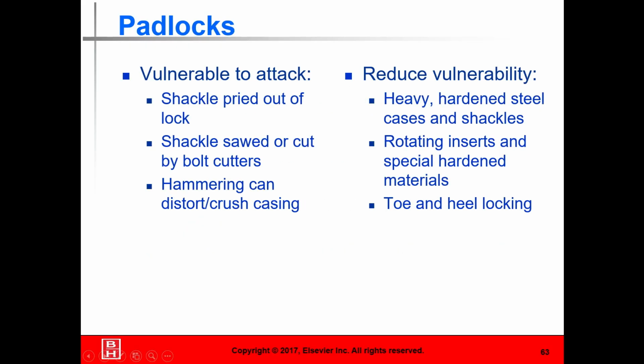Vulnerabilities of the padlocks: shackle pried out, shackle sawed off, hammered to destroy. To reduce vulnerability: heavy steel, rotating inserts, and toe and heel locking. These are some of the different things that we need to take into account.